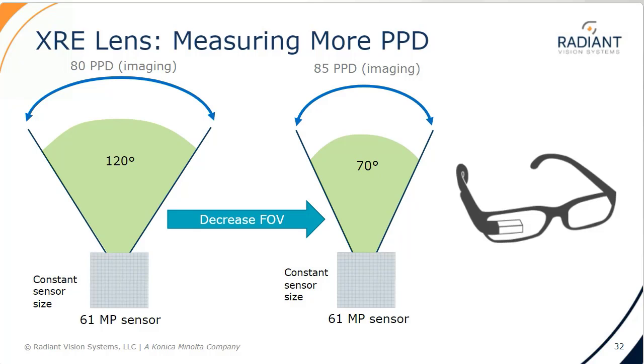As a general rule, in imaging, smaller fields of view are associated with higher spatial resolution and clearer images. Considering this, a narrower field of view can increase the accuracy of results for characterizing qualities like MTF or focus quality, which rely on image clarity for accurate measurement. In these cases, manufacturers can apply the XRE solution to test displays with the increased accuracy.